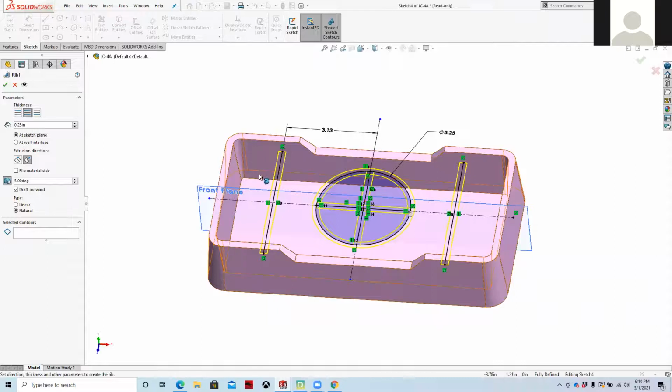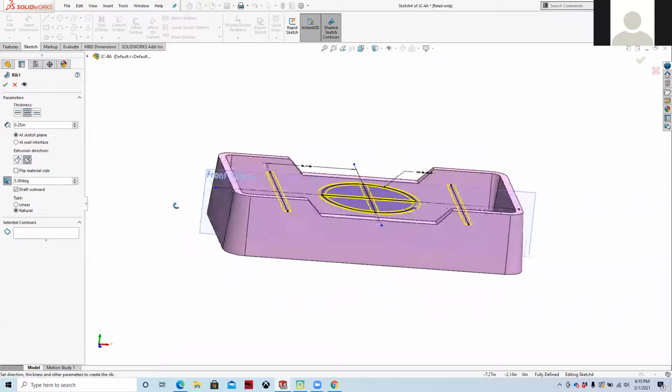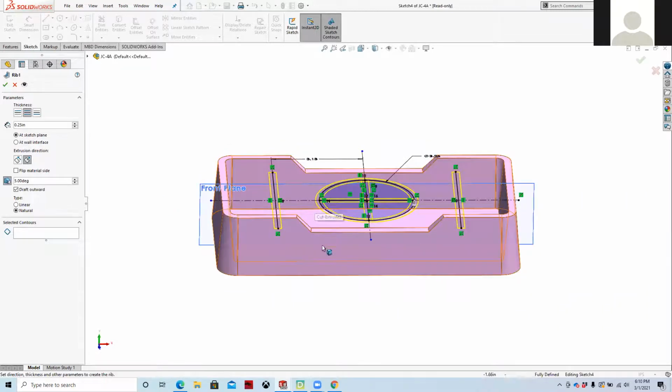In other words, it's going to offset 1/8 of an inch to each side of that geometry, and then it's going to taper it down 5 degrees. We'll apply a 5-degree taper angle to it, and we're not going to get into adding these additional contours to it. And so when we apply this, basically it's just going to extrude that down with a 5-degree taper.